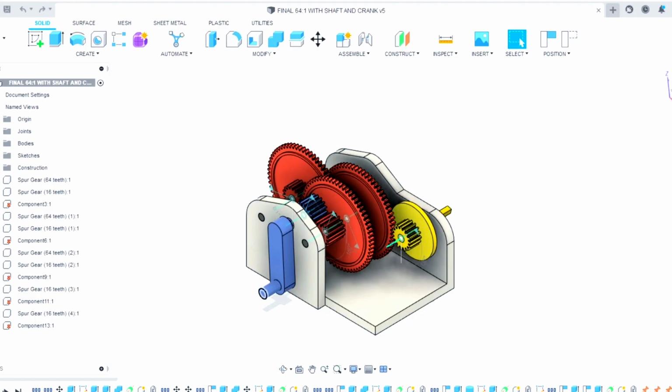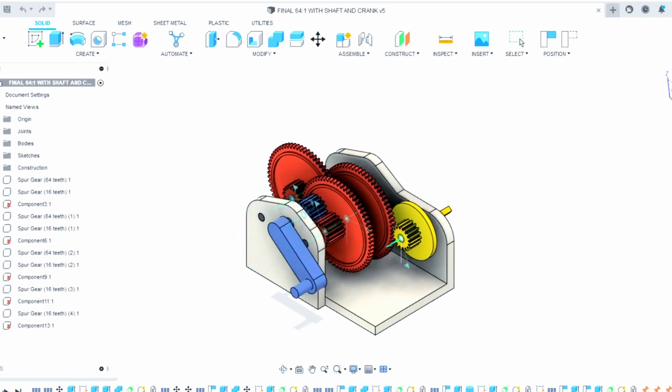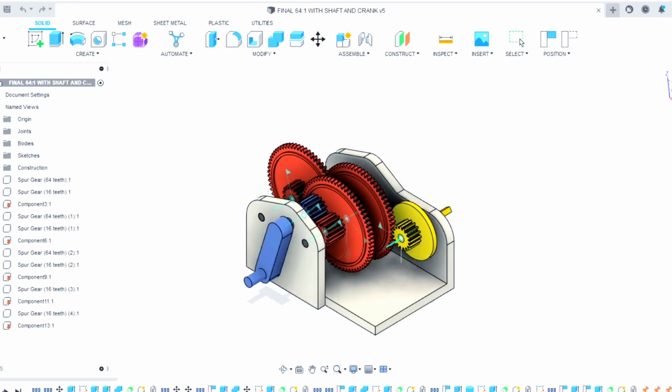We are now seeing the simulation of the gearbox, along with its different perspectives or points of view. The software used is Fusion 360. By means of manually rotating the crank in the software, the rotation is produced. An automatic simulation of the entire gearbox can also be achieved by right-clicking joints and selecting Animate Model. Here are the different perspectives of the gearbox simulation.